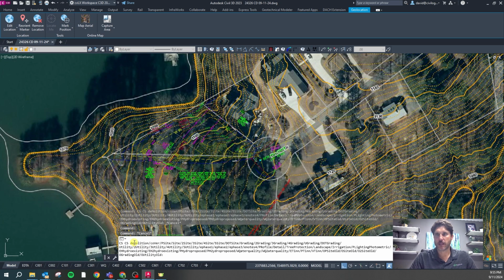So the capitalized letter gives you a clue as to what layer to go to. So I hit M if I want to go to the existing conditions or demo. I hit V to go to the cover. There's actually no cover in model space. The cover is over here in paper space. PS is for preliminary site. S is for site. We have multiple sites.